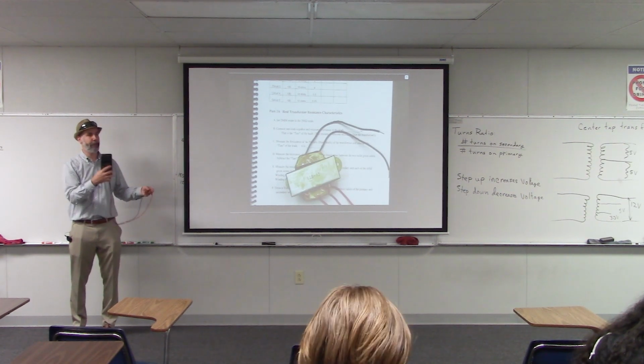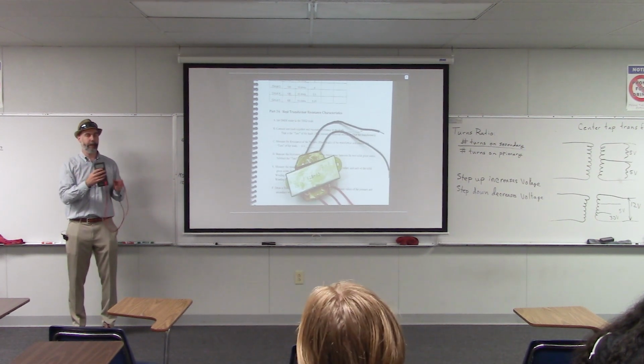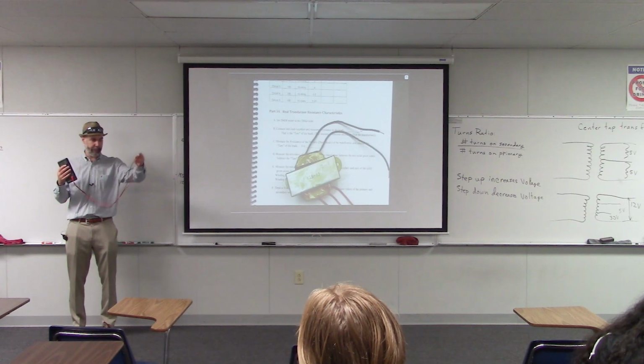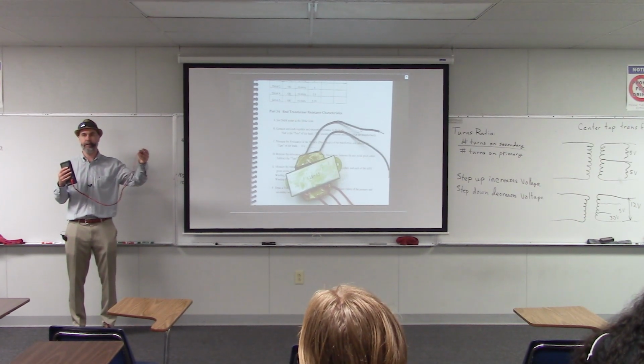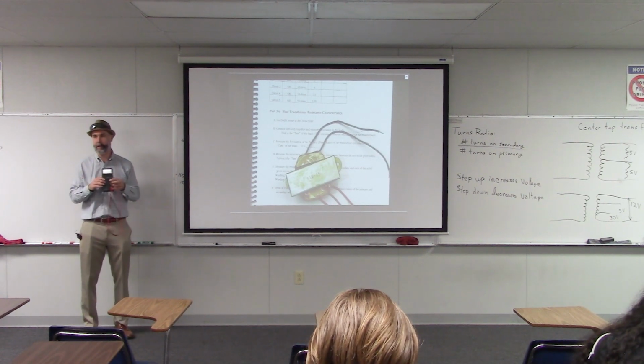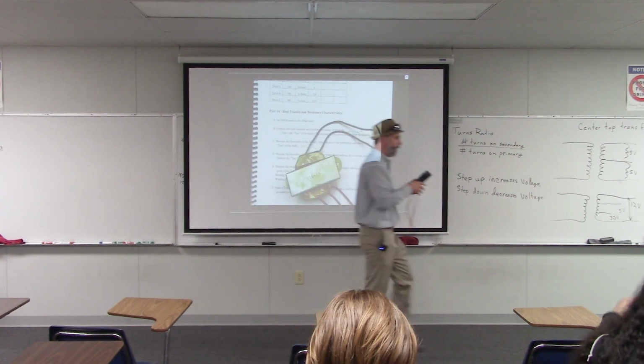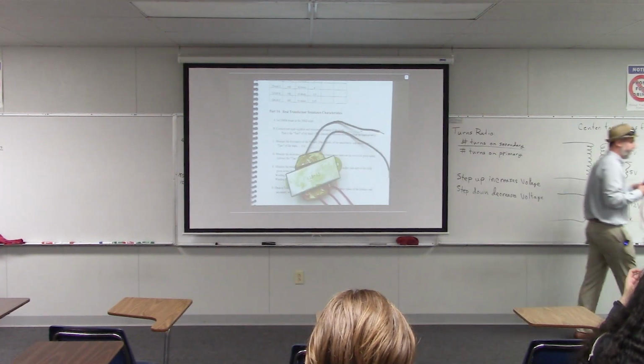So it's actually going to show you a resistance on that screen. And that resistance is the resistance of just these leads by themselves. So you're going to write down that resistance. That's called the tare, T-A-R-E. That's the tare resistance. That's the resistance of just the leads by themselves with nothing else.